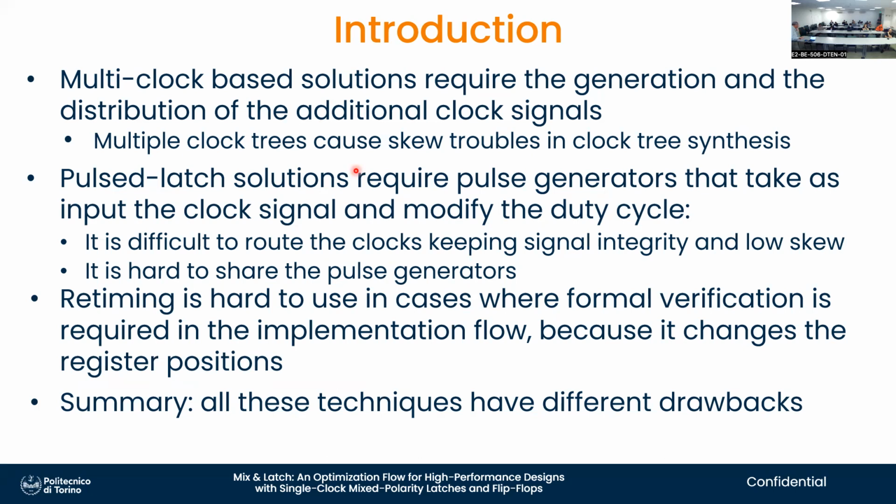There is also a third way of doing things, which is you don't ask the designer to come up with very well-balanced pipeline stages. You ask the designer to come up with correct register transfer logic. And then in logic synthesis, or even during placement and routing, you start moving the flip-flops back and forth.